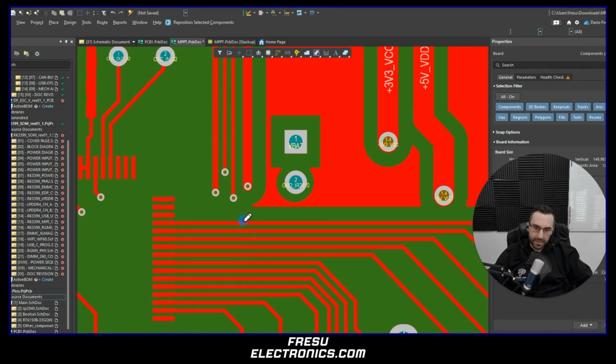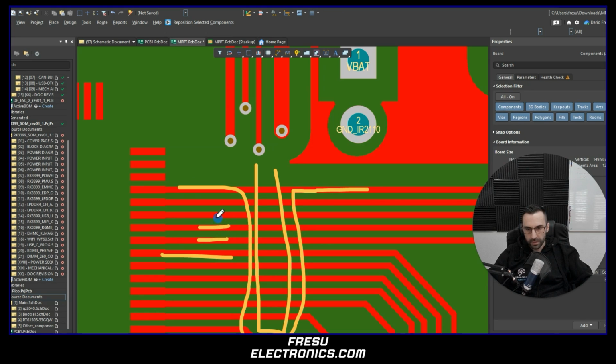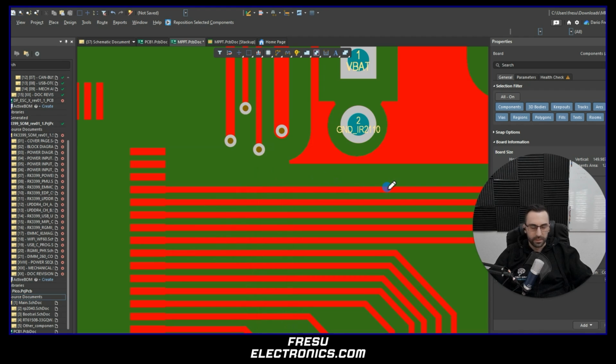So imagine what happens if I introduce the cut in here. Then the signal in here to flow back to the source has to go all the way here. And also all these signals in between will see that there is a signal going under them. And this is going to cause signal integrity, but also EMC issues.